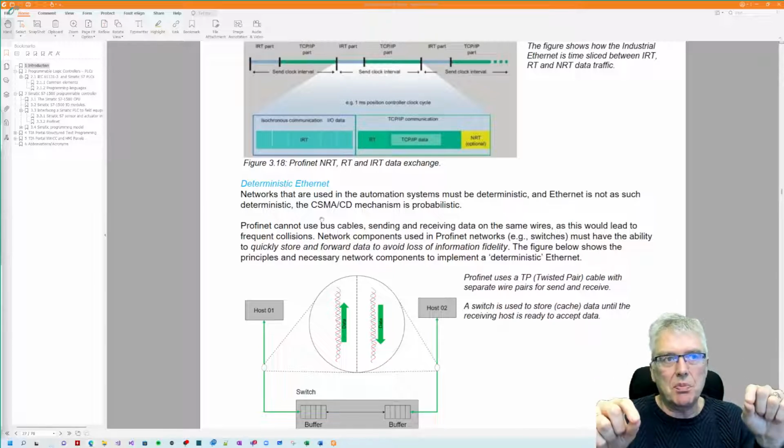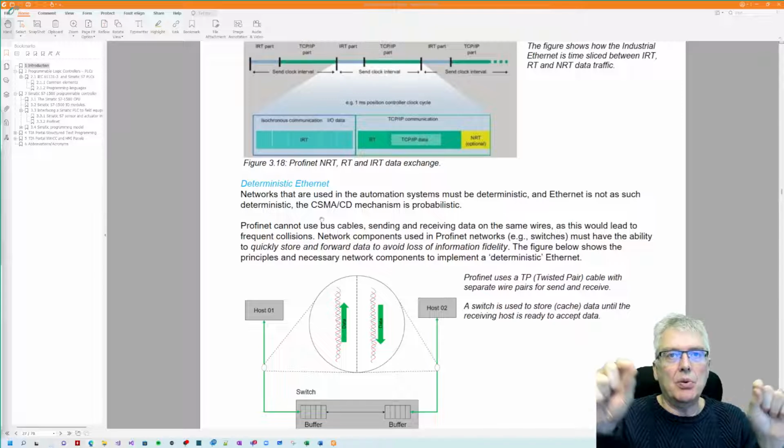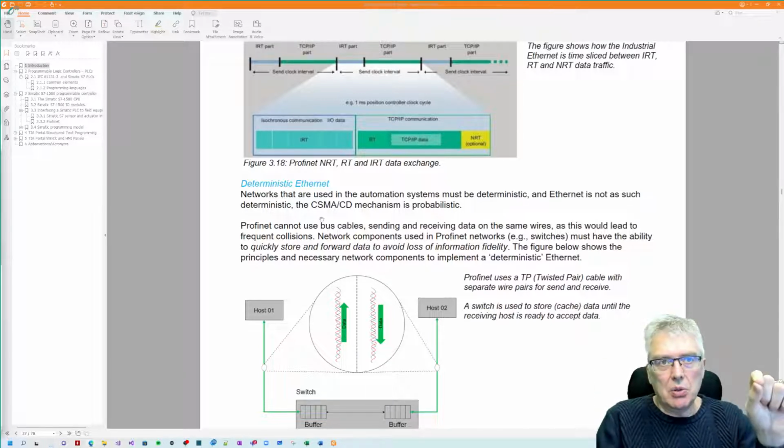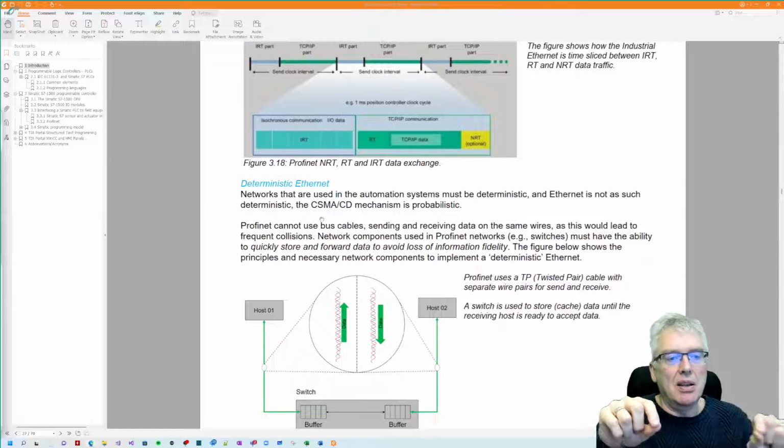That's not what I'm transmitting. And what all the devices do is they stop transmitting, wait a configured time, which is not equal for all devices, and the one with the shortest waiting time listens to the bus: okay, it's free, I can send. And the one with the longer waiting time listens to the bus: okay, it's occupied. Wait till the first one is done, and then they again listen and say, okay, send.